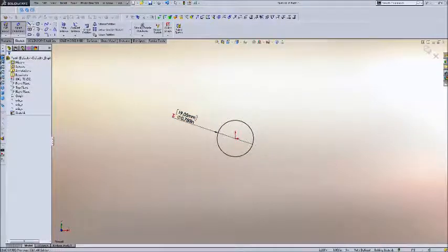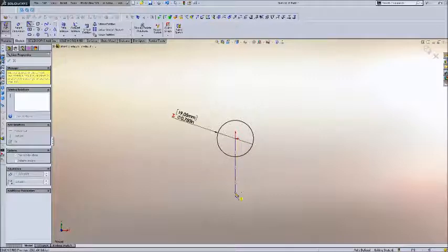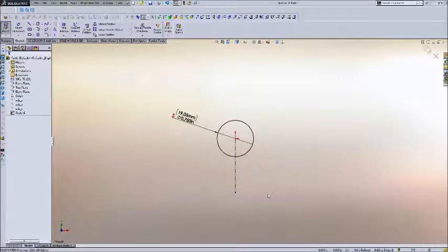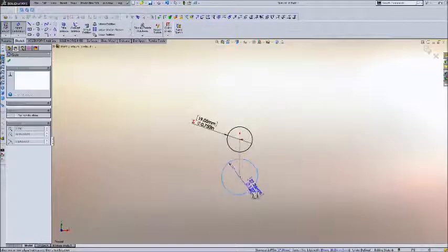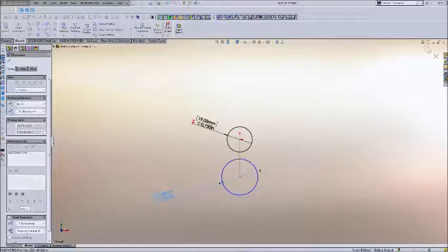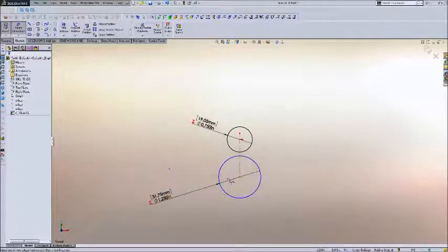So now I'm going to draw a center line, because I like connecting my gears by center line just to show the path that everything's going to take. Make a new circle. I'll do the exact same thing, except it's going to be 23 teeth. So my outer diameter is going to be equal to 23, my tooth count, plus 2, divided by 20. So 23 plus 2 is 25, over 20, and that's going to be 1.25. So 1 1/4 inches is going to be that size.